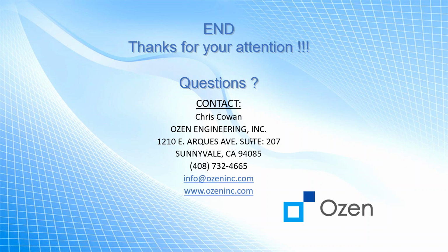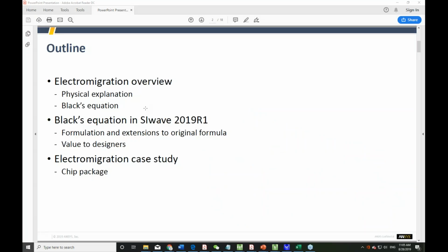Let me quickly start sharing my screen. Okay, so today's topic will be electromigration in SIwave. Just a general outline for today's webinar: we'll go through an overview of electromigration, the physical explanation as well as Black's equation, and we'll take a look at how Black's equation is implemented in the SIwave 2019 R1 version.